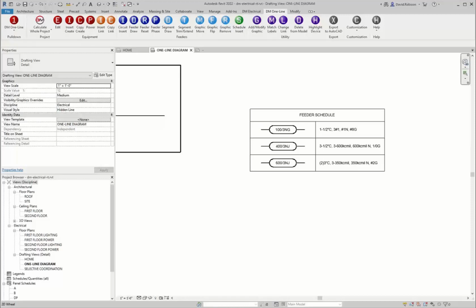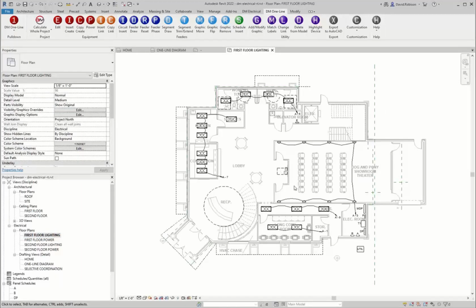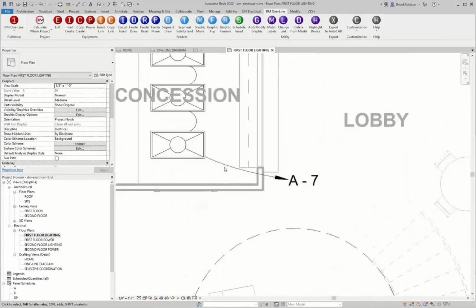The answer to that is that we actually let Revit handle the drafting of the tick marks, and that's typically on the plan views where you're looking at those. So those are on your home runs. So we let Revit draw the tick marks, and then our software just does the sizing of everything. However Revit tick marks work, that's what you do for your tick marks, and then you just use our software for sizing them. For your labeling, you'll want to use the Design Master shared parameters.